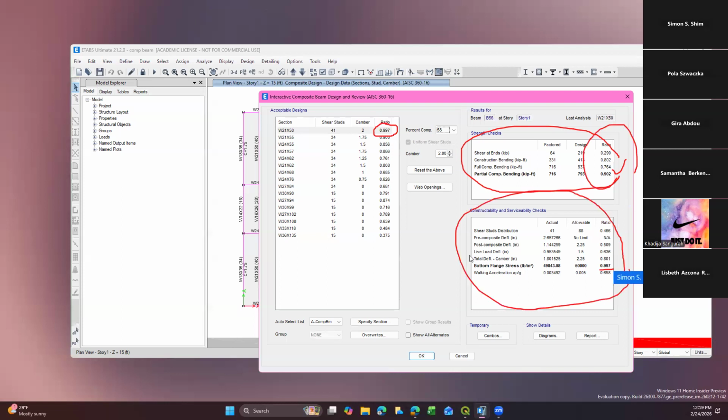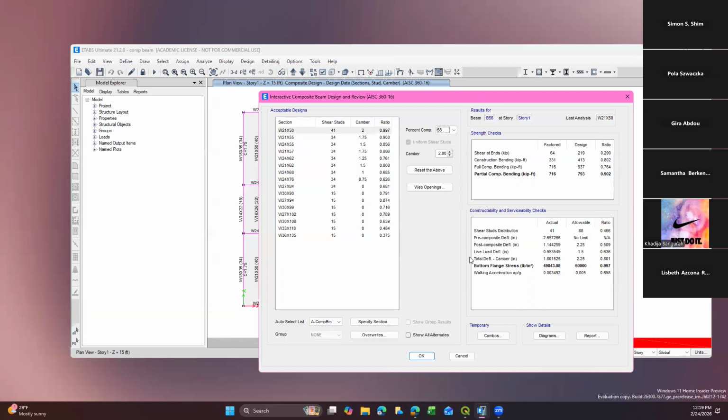So here we're going to talk about deflection. Now we're going to move to the strength check and deflection check, right? I assume everybody is aware of the deflection serviceability check, because in any beam design you need to choose the member size for strength. Your bending and shear capacity should be greater than your ultimate forces, right?